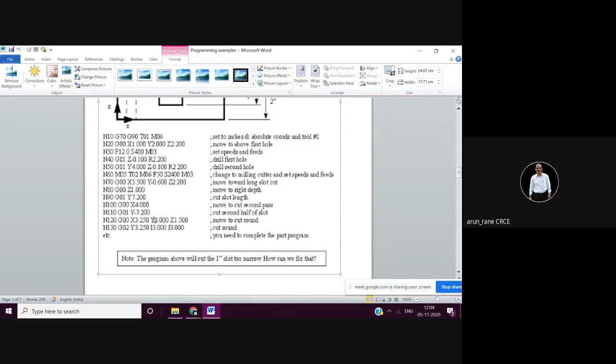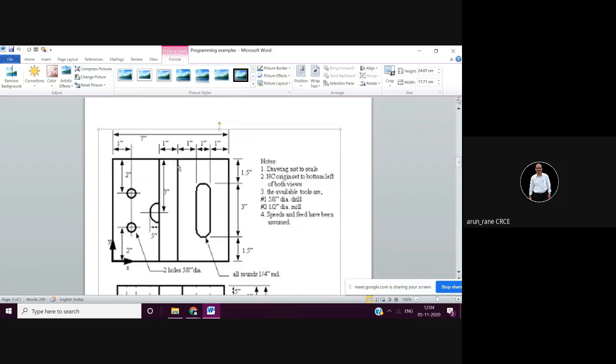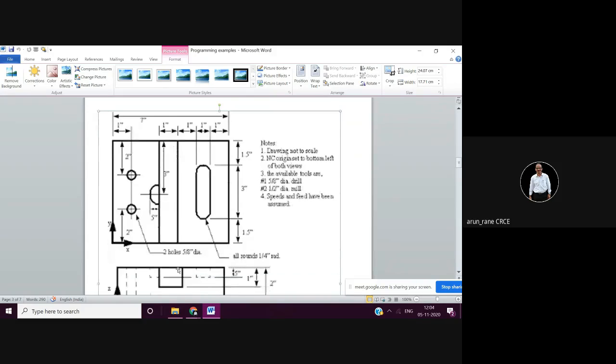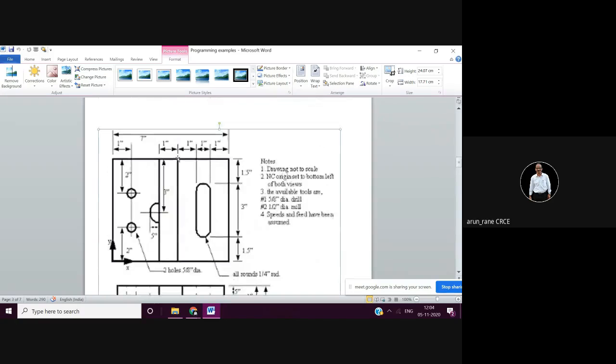But whoever wrote this program has incremental in mind, then he should have used G91 somewhere. Somewhere means here, right after G01, he should have used G91. Then it is yes. Then also there is a mistake. Now he moved to X4, X4 means the center line will be here. Understand? X4 and then from here he is going 7.2 minus. Now 7.2 minus means with respect to zero, 7.2 minus, that means the cutter will come all the way here, 7.2, and is traveling along this line.